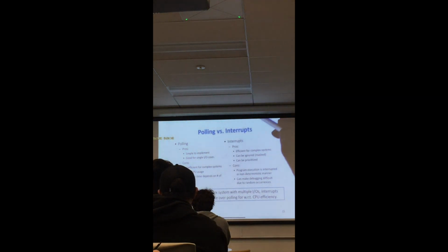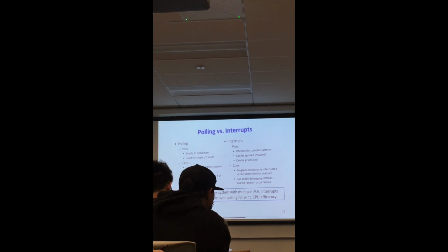So, for example, if you have two interrupts that appear at the same time, the CPU will decide which one has a higher priority to be processed. And interrupts can be nested. That's the biggest problem. Because with one interrupt, another interrupt happens. When another interrupt happens, the stack is growing and you never end up leaving. So this may happen, and debugging that is very difficult.